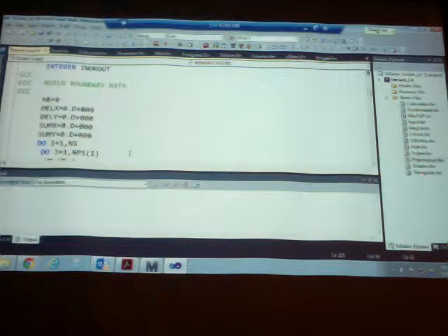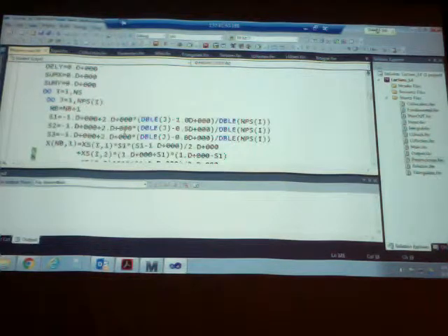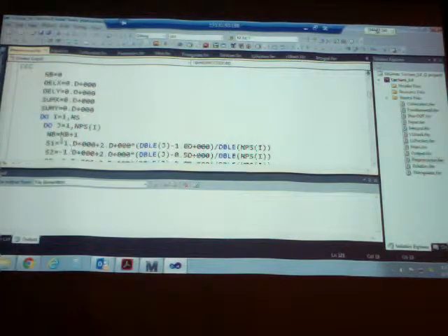First, it builds boundary data. It goes through some algorithms that you can just take your time to read. It basically goes through all the splines, uses the discretization of every spline, and uses quadratic shape functions, the same quadratic shape functions that we've been using, to put in boundary elements. And that's it. I already tested it, works fine. At the end of the day, it is increasing a counter called NB. That's the number of boundary elements. So the number of boundary elements is basically going to be the number of splines times the number of boundary elements that you specify for each spline.